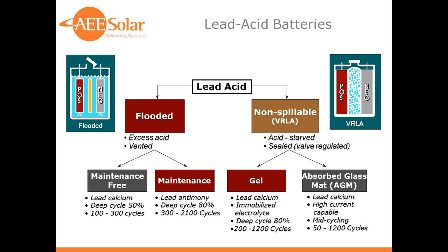So in the flooded section, there are maintenance-free flooded batteries. Very likely you have one in your automobile, for instance. They're very often lead calcium, but don't have a lot of cycle life. Maintenance batteries in flooded form are liquid batteries, and you do have to add fluid to them. You do have to service them, but they're designed for deep cycling applications, even up to 2,100 cycles at an 80% depth of discharge. And I'll explain depth of discharge a little more in a future slide.